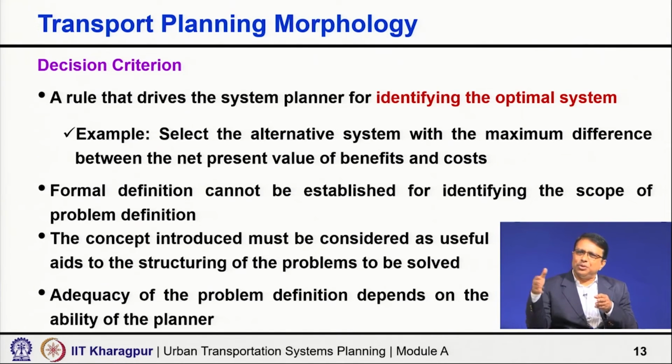The traffic benefit also: you develop a road, and the traffic, maybe for 15 years or 20 years, that is going to use the road gets benefited. So, they come at different times. So, you bring all the discounted benefit and all the discounted cost, and then you compare and say whatever gives me the maximum difference means my gain is maximum there, right.